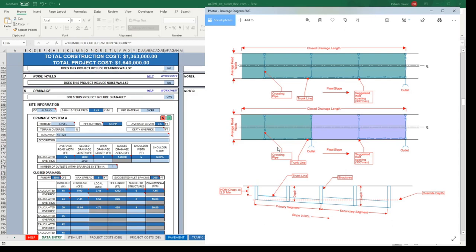This is very handy for roadways where you might be required to drain, let's say a mile. Well, in all practicality, you'll never have, or should never have, a drainage network that is a mile or 2 miles in length. You would get very deep, and the pipe size would get insanely large.